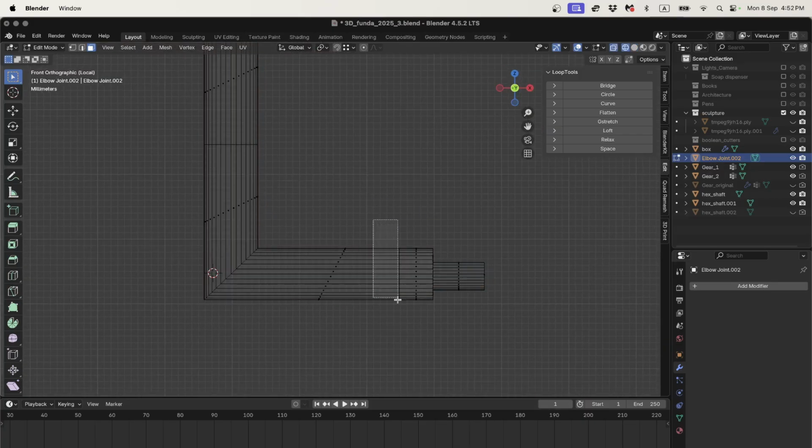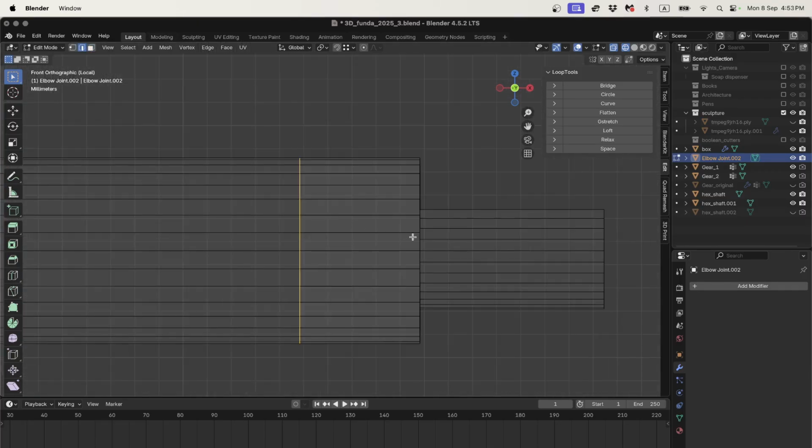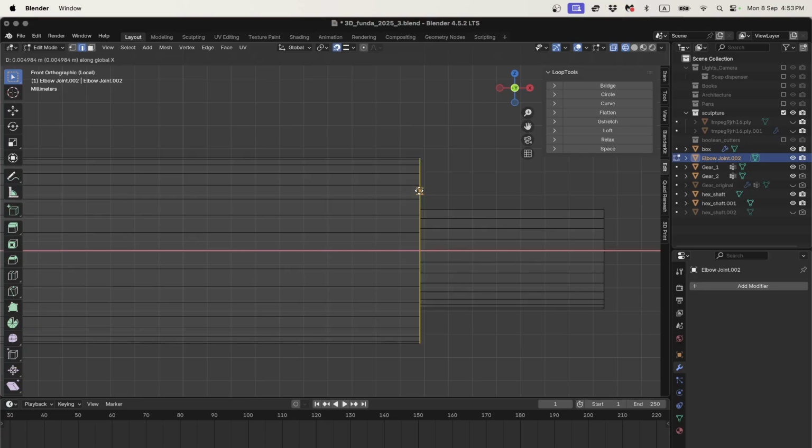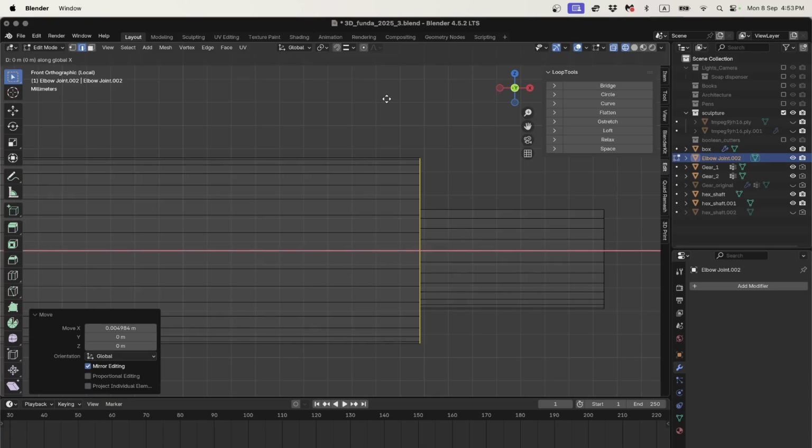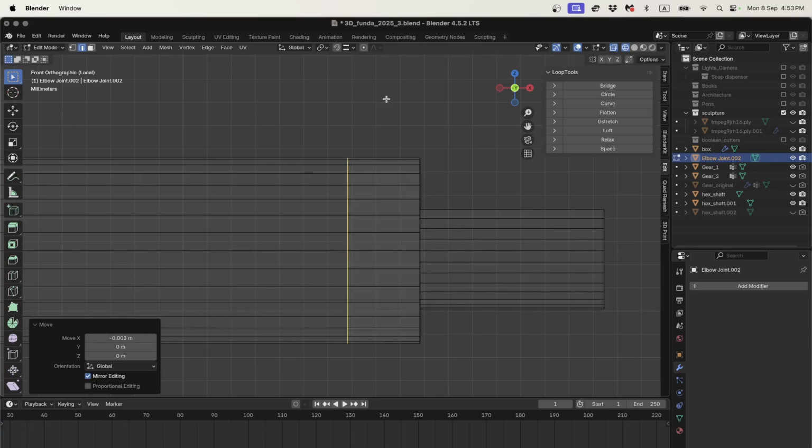All right, so let's just finish off making that little flange. I'll go into wireframe, grab, oh, I need to be in edge select, grab these edges, and let's be precise. Let's make it exactly 3mm. So I'll snap to this edge, GX, turn my snapping on, GX, and now turn my snapping off, and let's say GX negative 0.003. Great, so that is now an exactly 3mm gap.